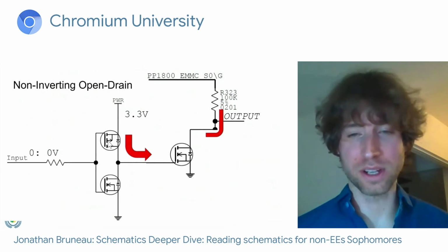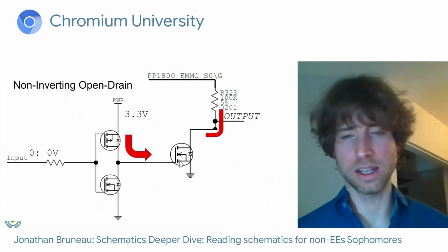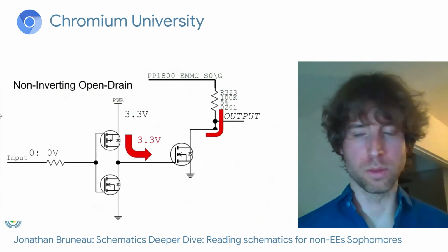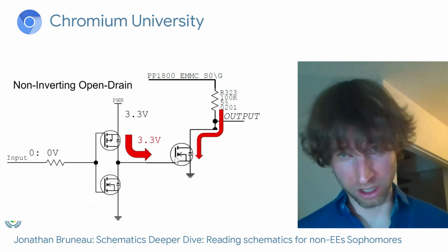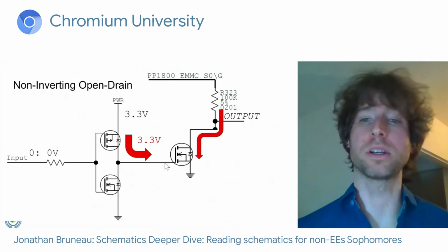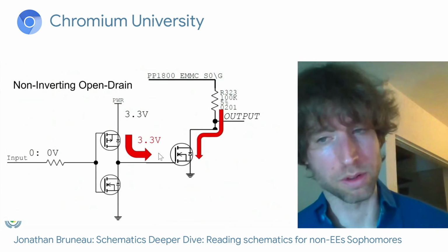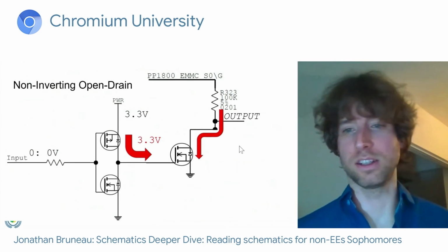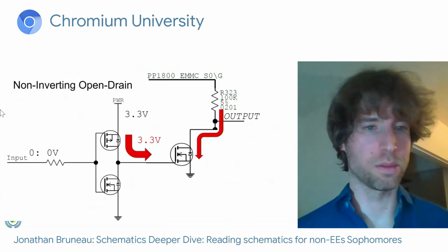This turns on the transistor, and so the energy comes from our power source and hits the gate here. So our gate will be 3.3 volts, which turns on our transistor here, which is an N-channel transistor, right? Because the gate to source voltage is now 3.3. And this is, again, just our classic inverter circuit that we had in the previous class.